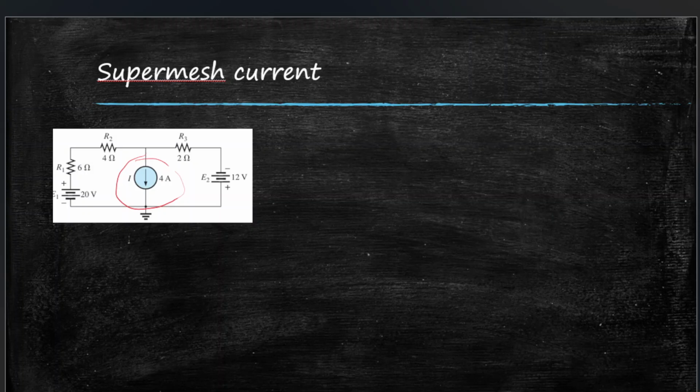So what you do for step 3 is you remove the current source. Remove the current source mentally, and you can redraw the circuit if you want for simplification. Now, as you practice, you will not need to redraw the circuit. You can do it all in your head, but for explanation I'll just redraw the circuit to make it easier to understand. So this is the circuit.